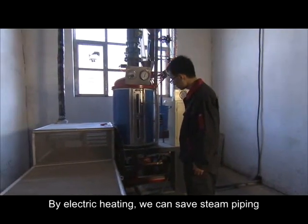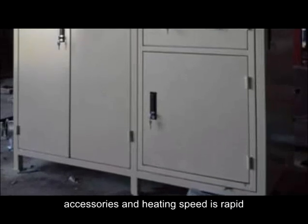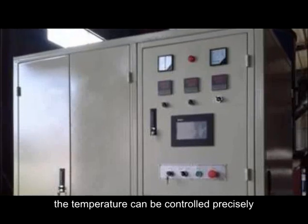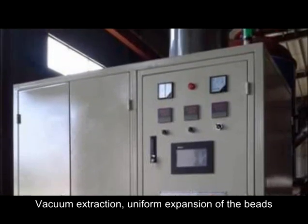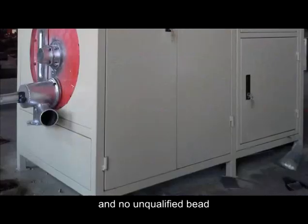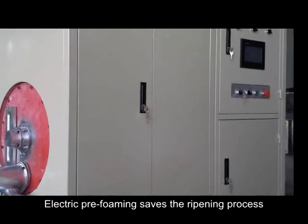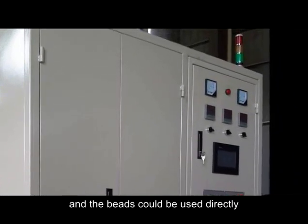The electric heating has advantages of saving steam piping accessories, rapid heating speed, precise temperature control, vacuum extraction, uniform expansion of the beads, and no unqualified beads. Electric preforming saves the ripening process, and the beads could be accessed directly.